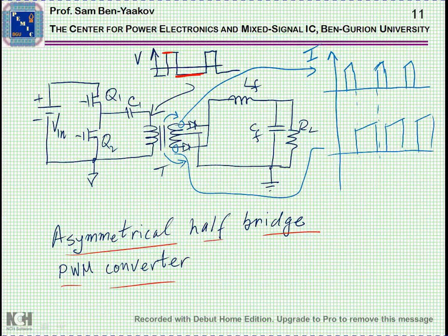This will cause asymmetry in the voltage here, asymmetry at the output, and what will happen then is that the diode conduction time will be different, and assuming a large filter capacitor, then you'll see currents in half of the windings like shown here. Obviously, the average here is, say, here, and the average here, so that we have two currents, but they are unequal, and therefore there is actually a DC current flowing in the secondary.